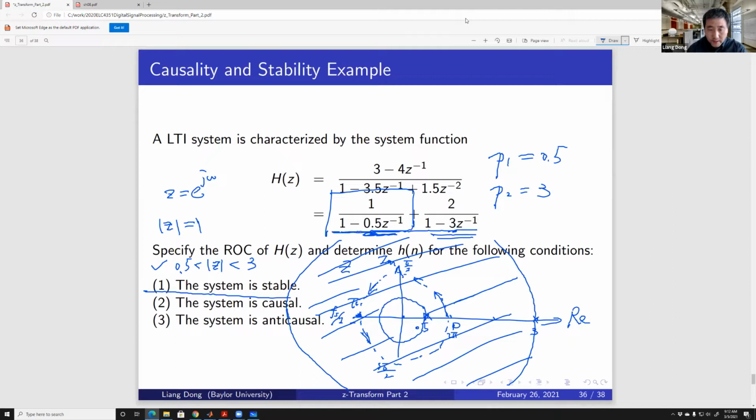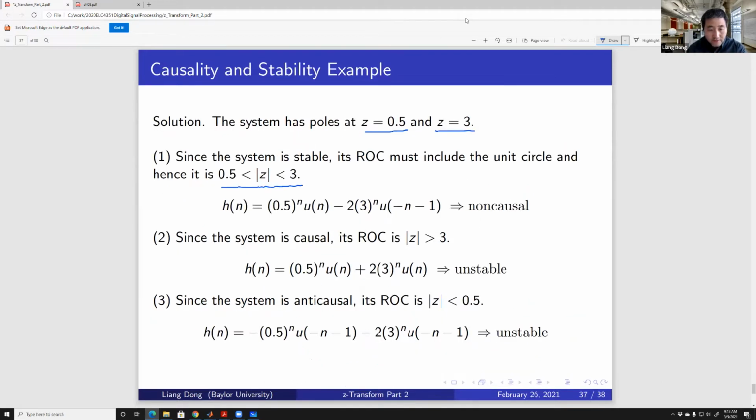Then for each part, the first part, what I meant is this part here. Now, if you look at this part, I got a pole 0.5, and you have this region of convergence exterior of this pole, a circle crossing that pole. Therefore, for the first part, doing inverse Z-transform, I'm taking this format, which for the first part only, that's the causal format. Causal is region of convergence is exterior of a circle. Right? So you got 0.5 to the power n, u[n].